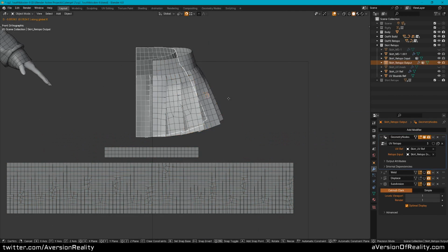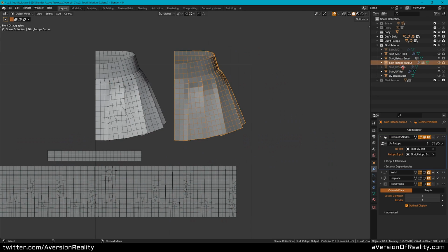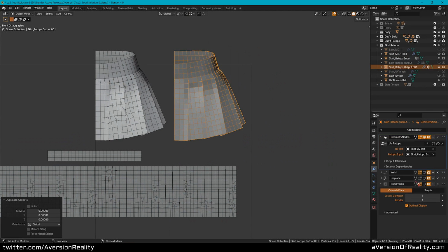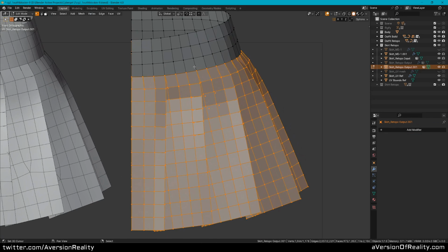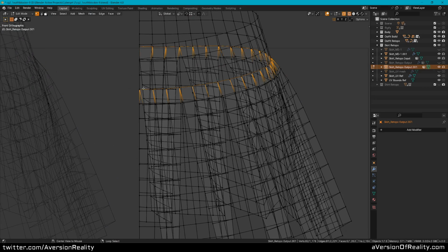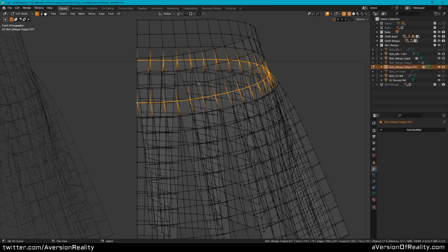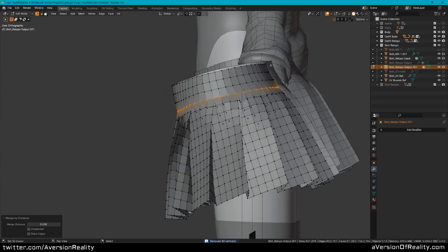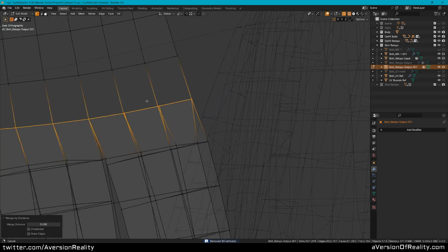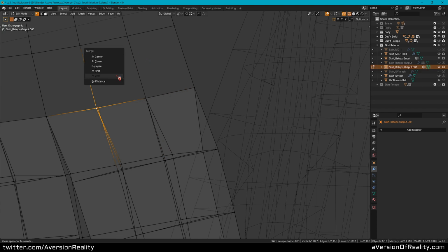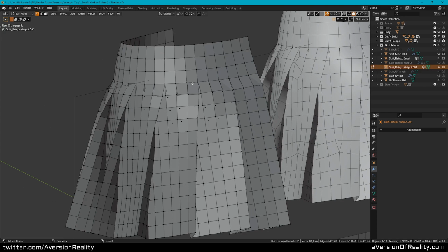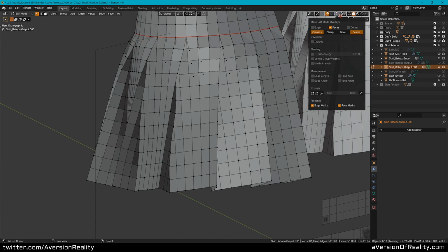Once all that is done, then we take this output in world space. I'm going to copy it, and without the displace on, do a visual geometry to mesh. And then there's a little bit of manual cleanup because these edges aren't merged. So select the relevant edges, do a by distance merge, and then check for any that were a bit off. It's a couple points back here. And then it's just a matter of maybe marking some edges as seams or with crease.